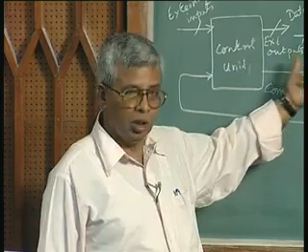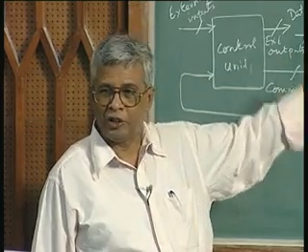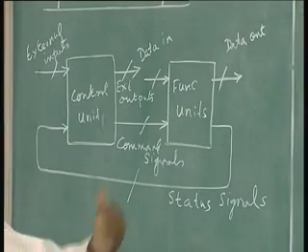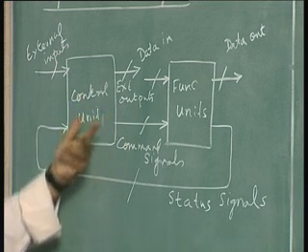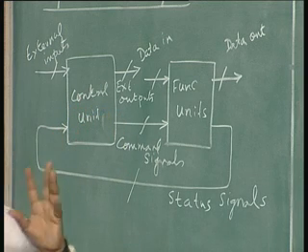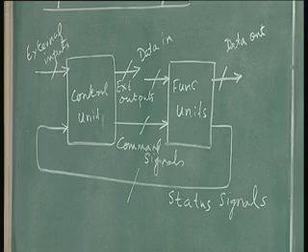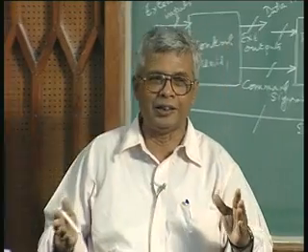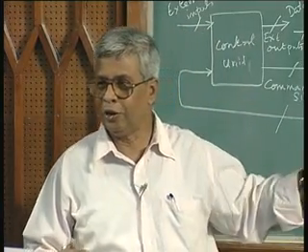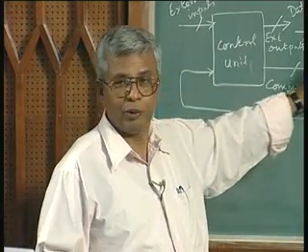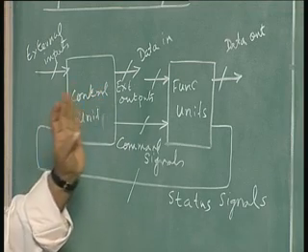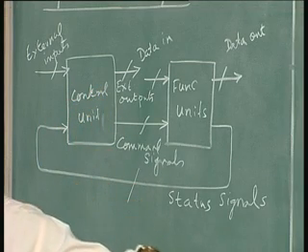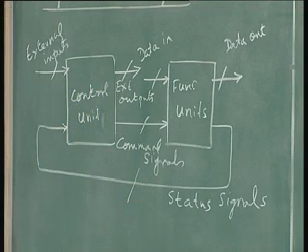And if there are no specific function units required, we put everything into this control unit. We did not call it a control unit at that time, we called it the full design, because the system is such a simple design. We did not partition into a control unit, and that is the extreme of this soft partitioning. The entire function unit can be gobbled up by the control unit. Of course, the reverse is not true. As long as it's a sequential machine, it has to go through states, and states are represented in the control unit.